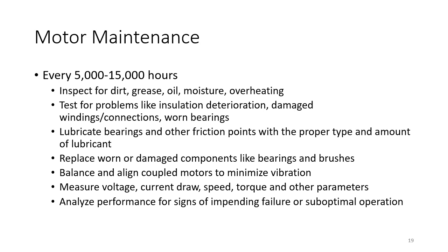You should look at motor vibration and attempt to minimize that. So that might be particularly where you've got a motor that's coupled to, say, a gearbox or to another mechanical device. You might want to look at balancing and aligning that coupling to minimize the amount of vibration. Otherwise, each time the motor goes round, it's being forced in different directions, and that vibration can affect the bearings and affect the life of the motor overall.